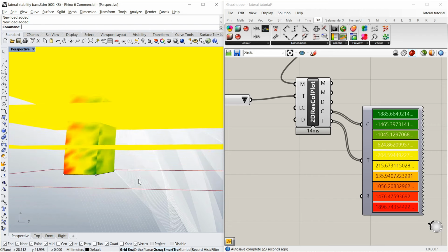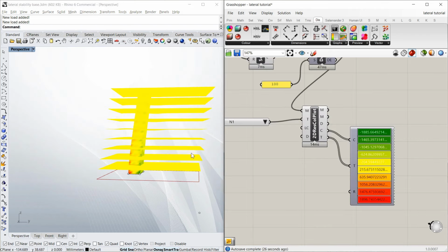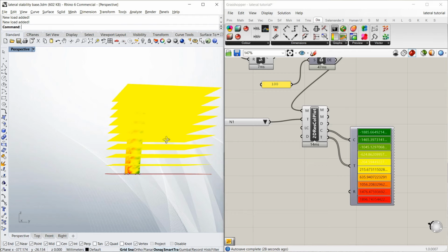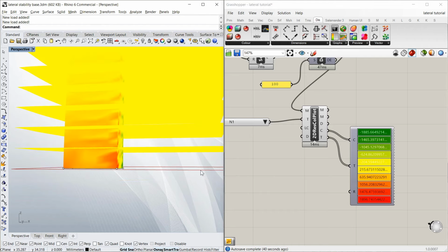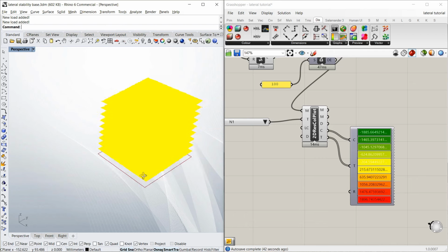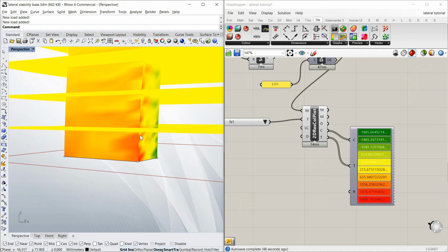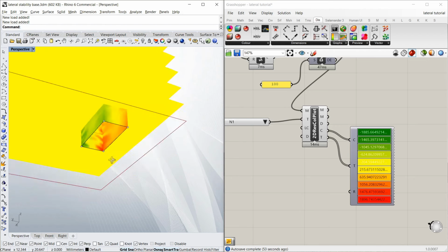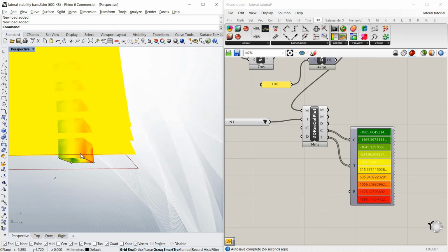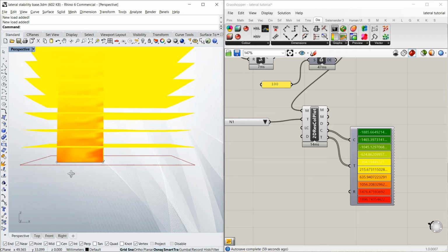So as this wind load hits the structure, it's trying to compress this side of the core, and it's creating tension. It's trying to crack the concrete on this side of the core, which is what you'd expect. The other thing is, as I said before, with the twist, you've got higher stresses along these edges than you do on the other side, because basically you've got more load over here than you do here.